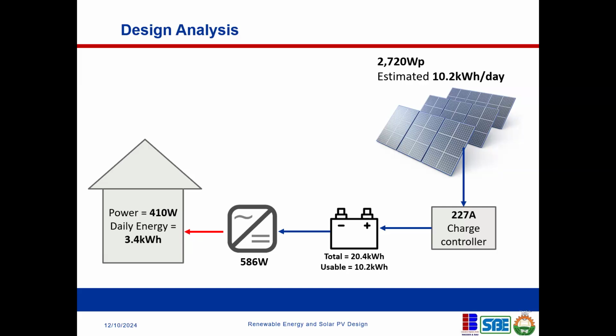So in this case, this is what I have also done. If there is grid in this system, then we can reduce this solar panel. We can reduce to even 1 day or even no day of autonomy. If there is no sunshine for that day, maybe perhaps this grid would have charged that battery for those 2 days of autonomy. You don't need to charge from the solar PV. I don't know if this is making sense. Yes, it makes sense. That with what I have in my house, the grid support, okay, so I don't have autonomy.